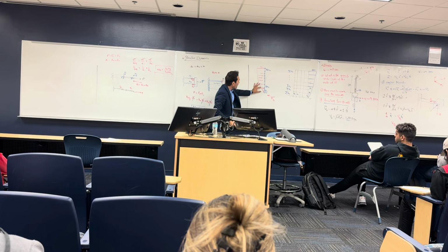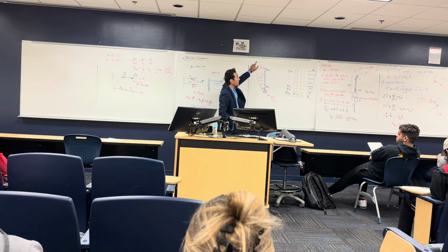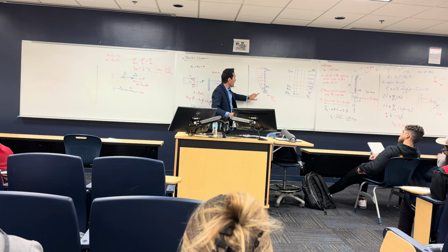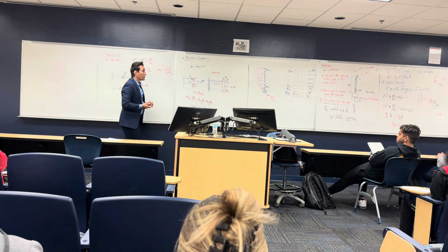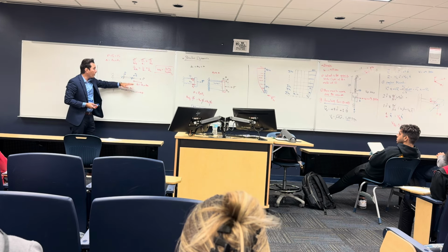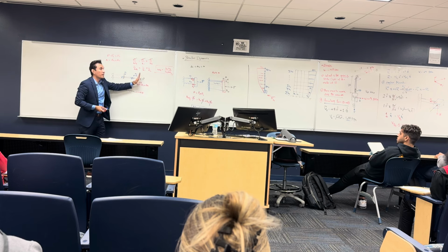Look at here. You have delta 1, and this delta is this delta plus this delta. So it adds up. The delta on the top is the sum of all the displacements from the other stories. Are these columns in parallel or in series? Series. You have delta 1 here and delta 2. If you add them up, you get the total delta. So these columns are in series.